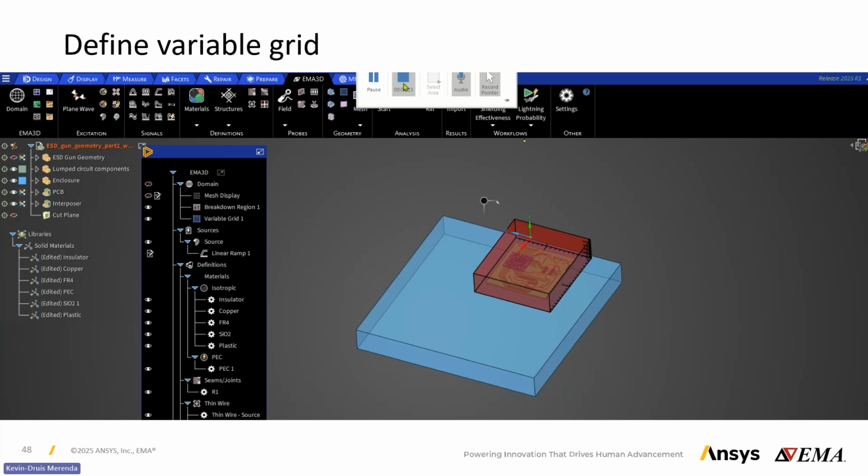As you'll see in a second when we visualize what the mesh looks like, the refinement in one of the dimensions has to extend all the way along the axis. It does help us refine the mesh size significantly across the whole domain, but it's not something where you can have the growth that is typical to FEM meshes. You have to deal with the way the grid grows in FDTD.